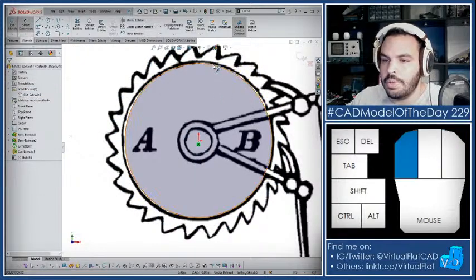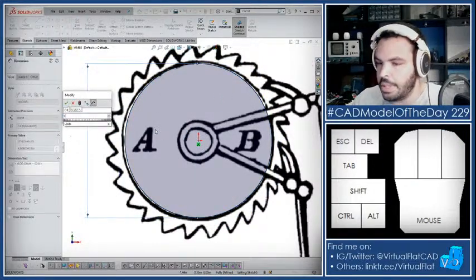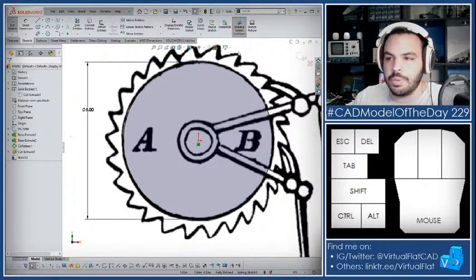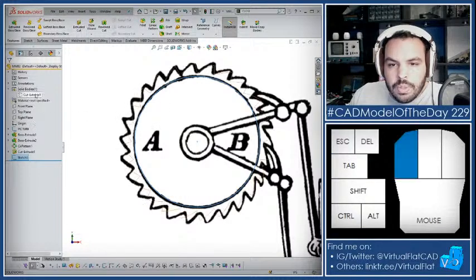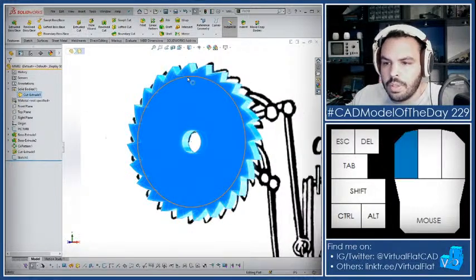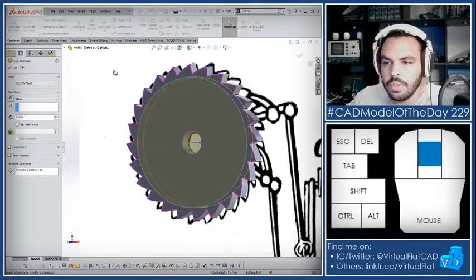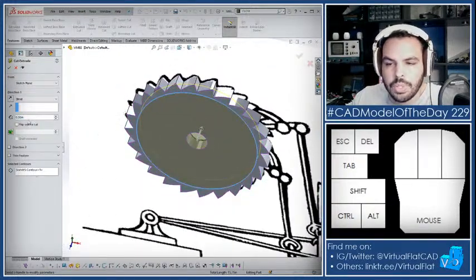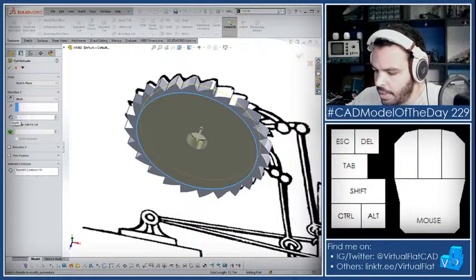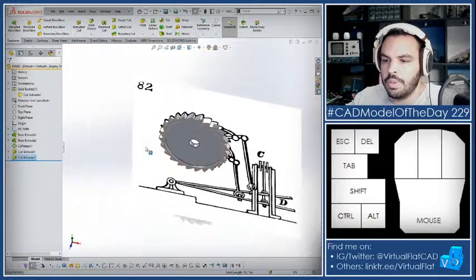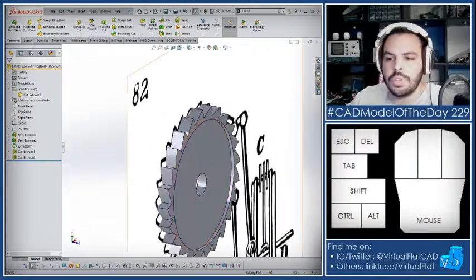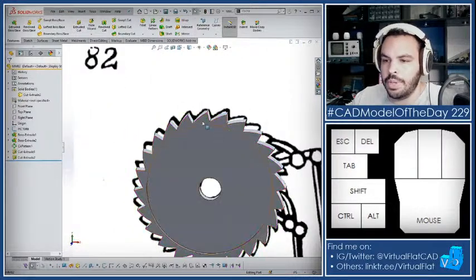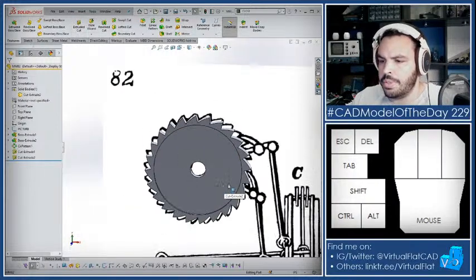Alright, so what does that want to be? Slightly bigger. Oh, that looks like that really wants to be 5. Yeah, that looks really good. Okay. Can extrude. And let's just say 0.125. Yeah, there we go. And you notice I didn't put a mid-plane, so I'm going to have to create a plane if I want to mirror this around.